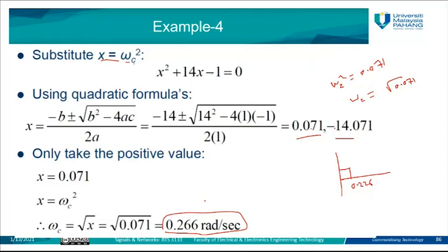If you have this transfer function, you know that the magnitude at the initial condition is 0 and at infinity is equal to 1, that means this is a high pass filter. If it's 1 and 0, that means low pass filter, and so on. And you have four equations to find the value of omega c and the value of omega naught for the band pass filter and band stop filter. So now, since you already have the transfer function for the filter, it's easy to draw the Bode plot.